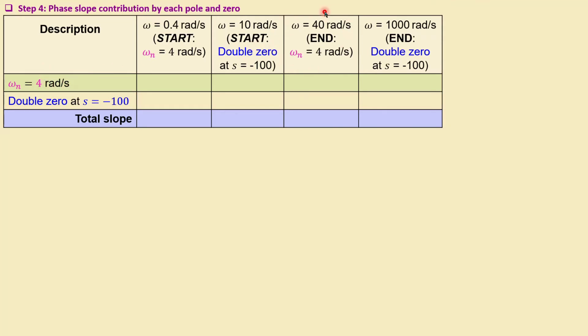It's shown here. For each order, for example for the poles, you will have a phase slope of minus 45 degrees per decade, and for the second order complex poles you will have minus 90 degrees per decade. That's shown here. So it starts here, it keeps that phase, but now it's ending and has a 0 degrees per decade slope. That's just the contribution by these complex poles.